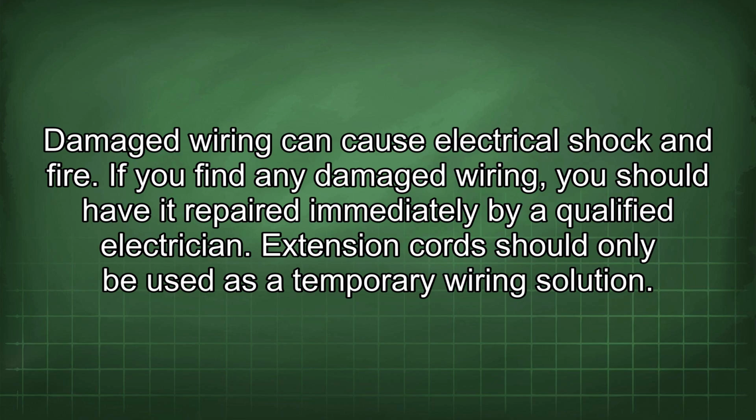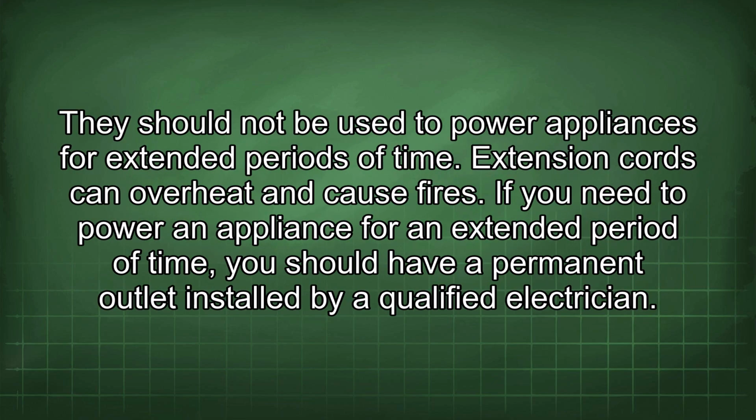Extension cords should only be used as a temporary wiring solution. They should not be used to power appliances for extended periods of time. Extension cords can overheat and cause fires. If you need to power an appliance for an extended period of time, you should have a permanent outlet installed by a qualified electrician.